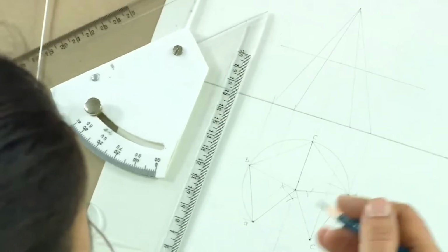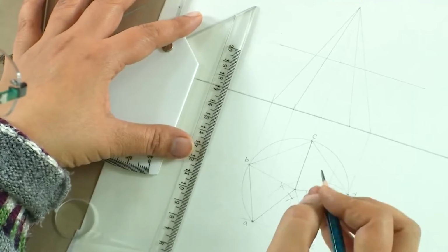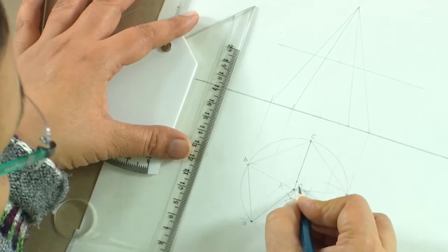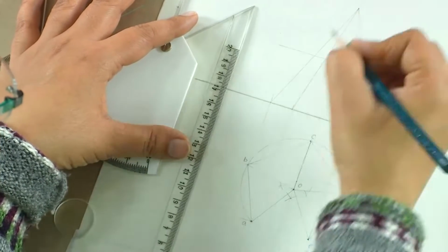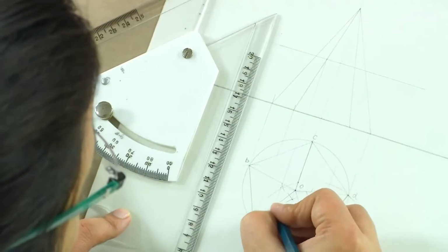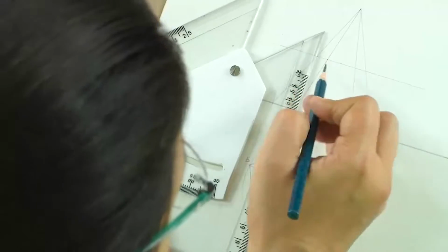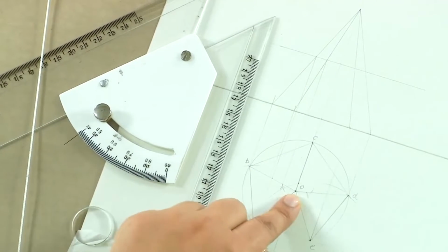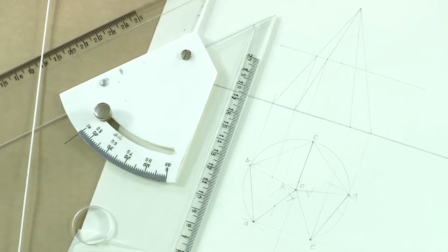Now, let us take the projections back onto the top view or the plan. Let us go one by one. This is O. Now, OA is this line. It is cut here. So, if we take this and bring it back, this is where it cuts OA. Now, let us go to OB. This is the point which is cutting OB, and we will mark this point on OB. This method is slightly different from how we drew the sections for prisms.